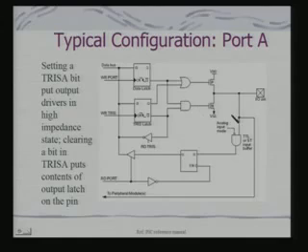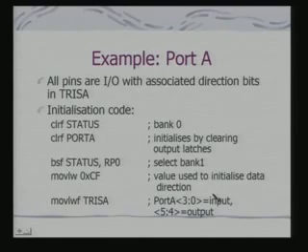And in many cases, even these digital I/O pins can be configured to get analog inputs for some other purpose, because these pins are multiplexed for serving requirements of other peripherals as well. So this is the basic structure. You can see that these are the two latches which actually record the data as well as the TRIS bit, enabling the direction of operation. Let's look at the code. So what is happening here?